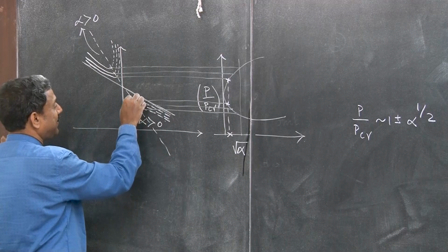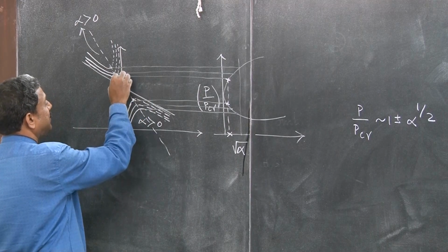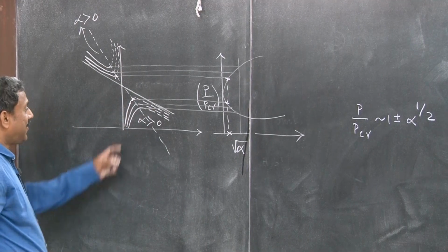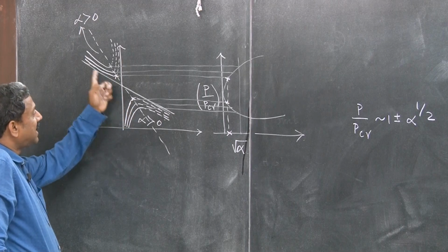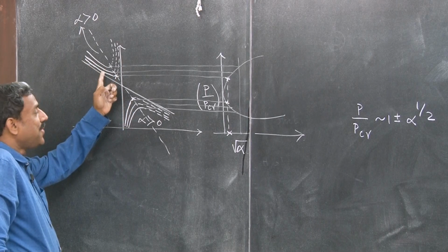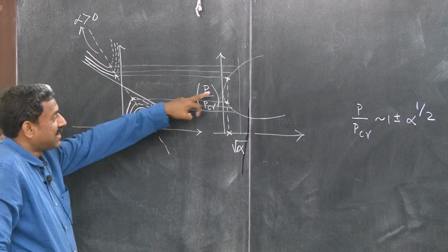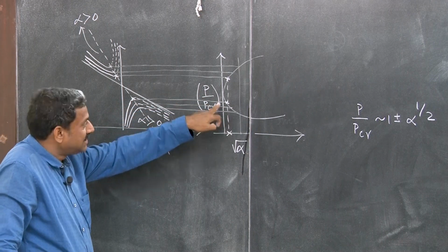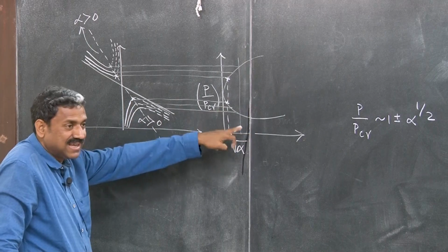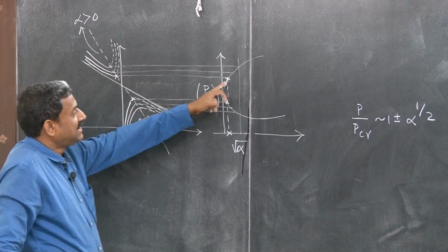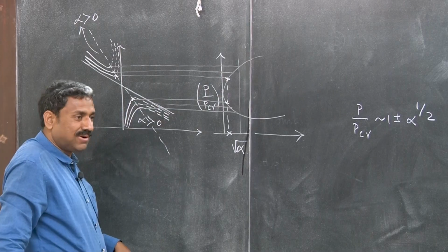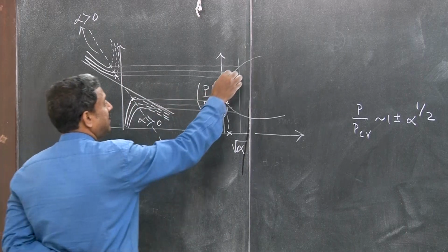So, this root corresponds to this, another root corresponds to this, okay, one is stable, another is unstable, clear. So, for this it is unstable bifurcation, that is why the load is imperfection sensitive, the load is decreasing. For the other one, the load is increasing. You understand that?